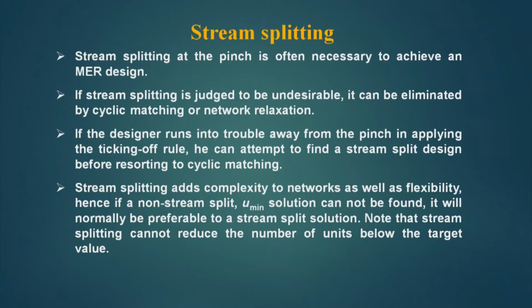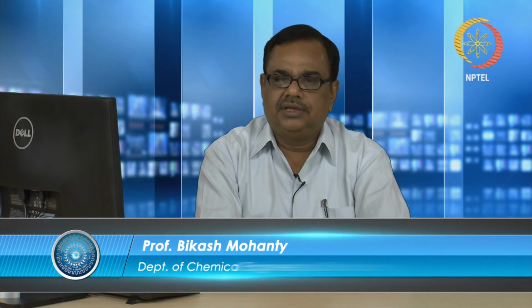If stream splitting is judged to be undesirable, it can be eliminated by cyclic matching or network relaxation. We will see in detail what the cyclic matching does and how the stream splitting can be avoided by cyclic matching, but it has got its own problem.